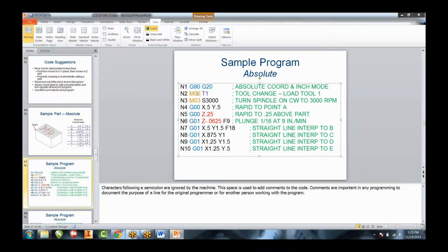Up in the measure, so tool change, it stopped the spindle, it went all the way up the top. The kids were like, well, it's going over to the position all the way up in the air. How do I know if it went there? Yes, that's partially true, but you always want it to go over to it and then down to it rather than down to it and then over to it. If you go down and over, there's chances that you'll run into the vise, you'll run into clamps, you'll run into bolts that are holding things into place.